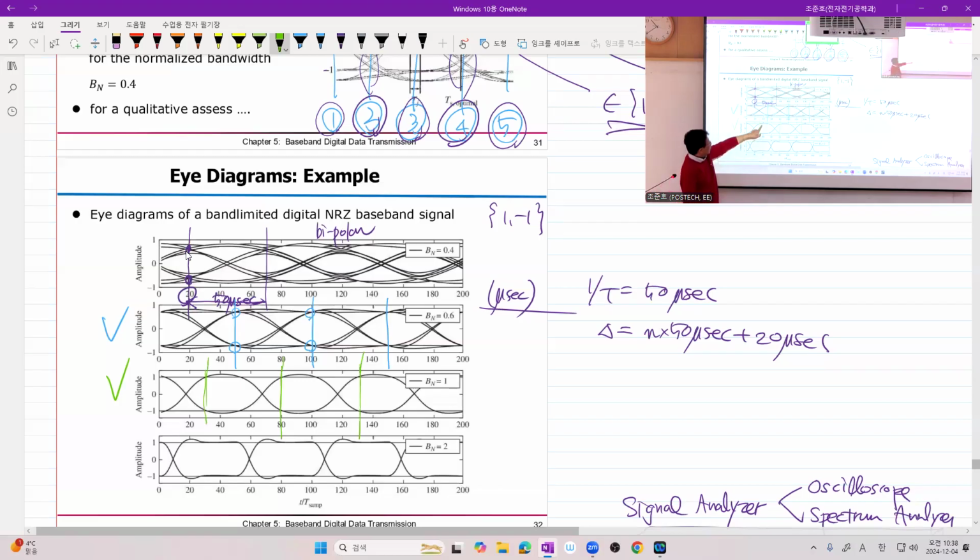See that? Even though at this time instant your signal is greater, you may have some effect from your ISI. The problem is that if this is almost a straight line, actually, this sampling instant may be better than that one, because anyway, if you sample here, you get a larger signal than this signal with some probability. So defining an optimal sampling instant is not unique.